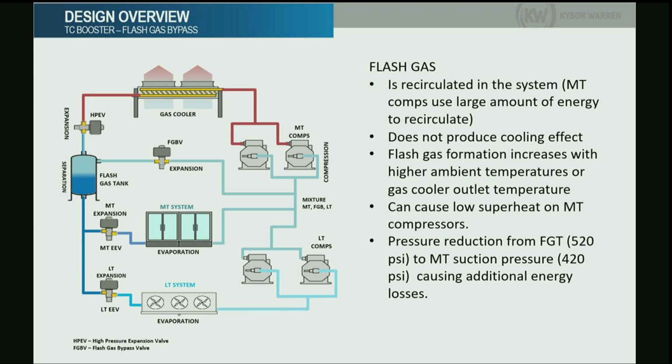What are you generally running on hot gas defrost pressure? Pressure will be above the flash tank, about 580. Okay, so not too high. No, not too bad. Well, for hot gas defrost, actually the pressure is not the important part. The important part is how hot your gas is going in, and how much gas you have.